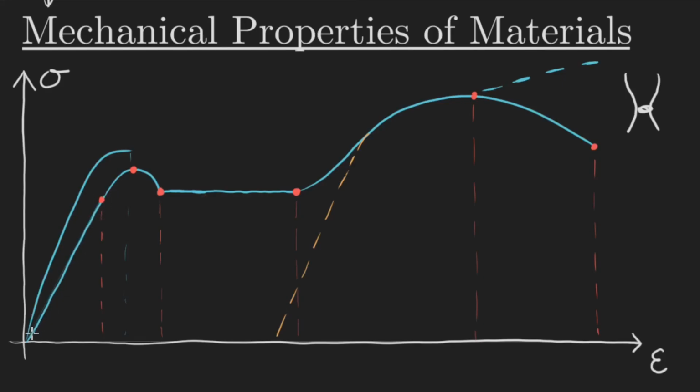So if I take something and I add this load all the way up to here, and then I release the load, I'll actually get a stronger material that can be in the linear region for longer, which is usually the region right before we say it fails. Like if you remember earlier, we were talking about the yielding stress being kind of like the condition for when it failed. So now the yielding stress would be up here. It would technically be closer to the ultimate fracture or failure, but it is useful in a lot of cases. And sometimes manufacturing processes will take this into account.